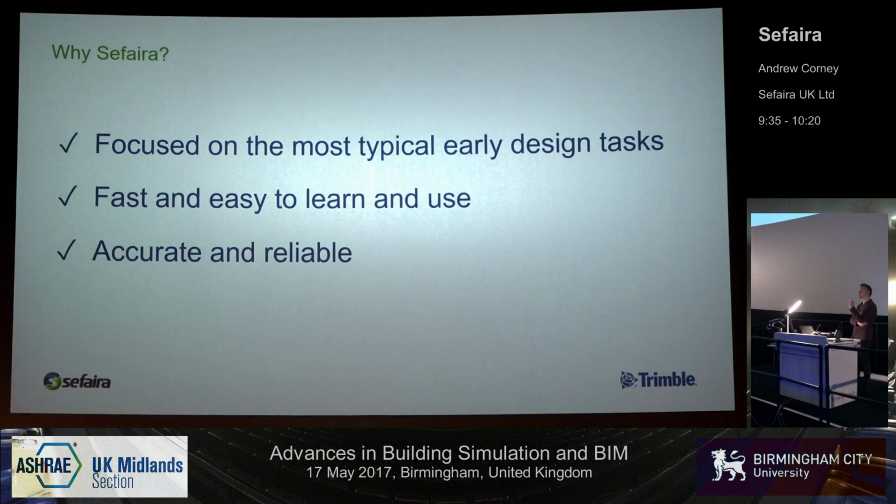So you can see on the study that I presented, it's looking at apartment buildings, school rooms with single-sided ventilation or multi-sided ventilation, but it's a single zone analysis. We will ultimately get to a point where we can do cross-flow ventilation. So it does use the airflow network calculation. But like essentially any bulk airflow modelling approach, if you put lots of windows in there, it's only going to do so much if it's all in the same zone, right? So you shouldn't expect having windows in lots of different places to make a huge difference to the results if you're doing a bulk airflow study and it's all in the same zone. Does that answer your question? It does, yes. Cool.